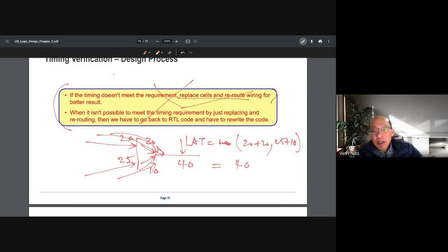The question is, when we have a multi-level logic expression, do we always have to optimize that to a two-level logic? We don't need to. Two-level logic is from the old days, when they had the PLA, which is only two-level, like a two plane array. So they reduced down to that and minimized it.